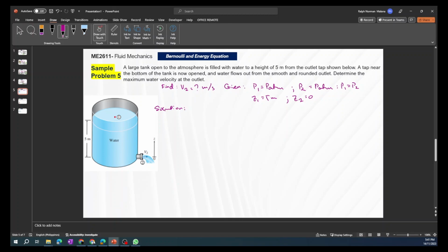So steady, meaning this one is very streamlined, steady flow and streamlined, and it doesn't really cause much turbulence. Okay, and the irreversible losses that we would experience in that tap are going to be neglected for the meantime here, since that is the main requirement of the Bernoulli energy equation. Okay?